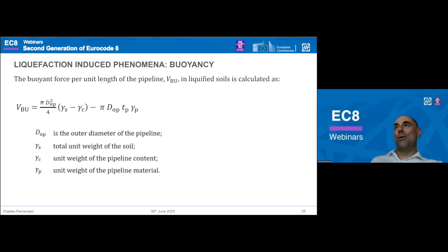So my experience is that you sometimes do the inverse thing. You calculate the maximum length of liquefaction, and then you can compare it with what is expected at the location, and then usually, or hopefully, you will come up with the answer, okay, it is decisive or it's not decisive. But this information is usually not readily available for all sites, so this has to be deeper investigated. So it seems quite easy, but the input parameter could be a problem.